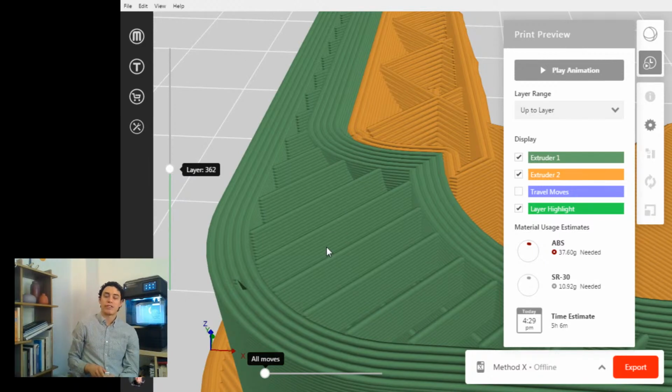And the shells are different from the infill, and from doing a solid print, because it does affect the print time. But if you're trying to create something stronger without necessarily having to do it completely solid, because that might not be the requirement, the shells are a better place to start. I think the shells will add way more strength than you would expect from just increasing the infill.